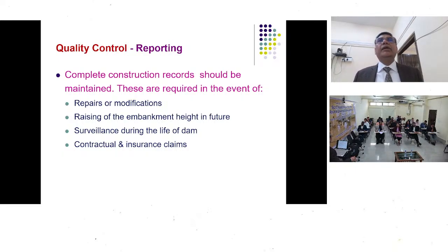There may be a requirement of raising the embankment height. At that particular time, these documents become very important for the designers to decide what type of material has been used, whether we can really go in for enhancement or not, whether we have to put the same section or the section has to be increased, whether the foundation treatment, what is the extent of the foundation treatment.